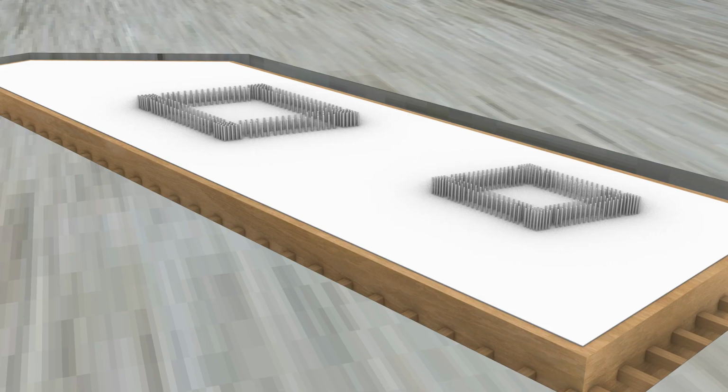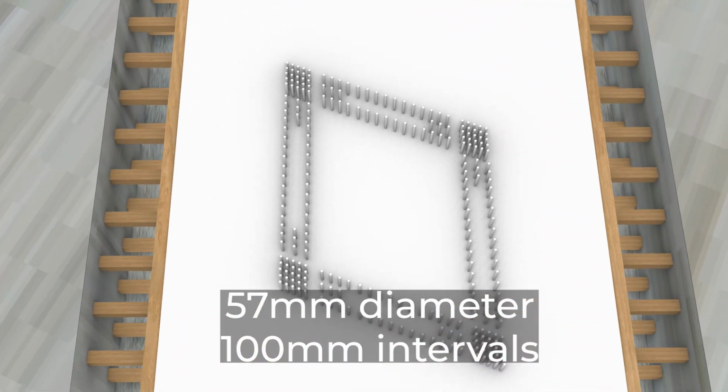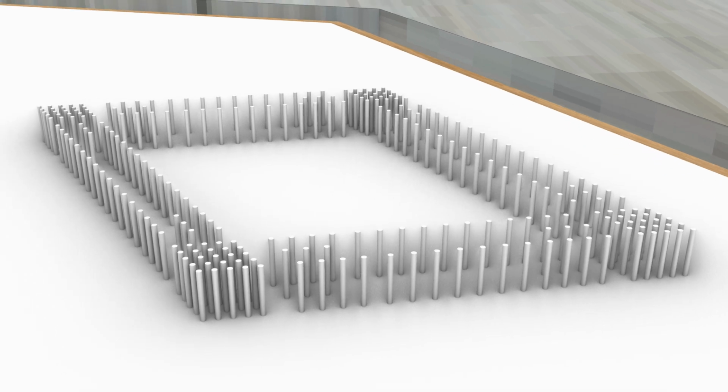Mega columns have a rectangular cross-section with 57 mm vertical rebars placed at 100 mm intervals. Unlike typical circular columns, rectangular columns have additional vertical rebars densely arranged at the corners to reinforce critical strength points.